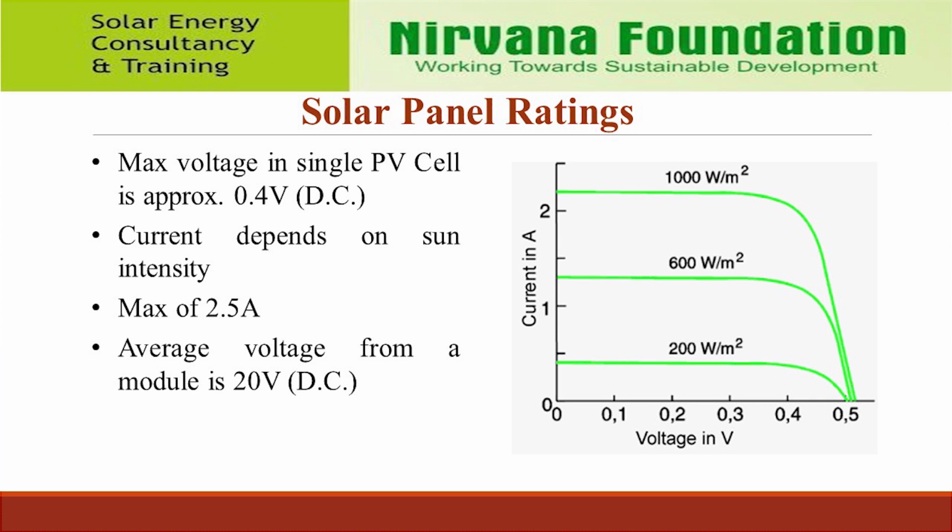The graph shows characteristics of voltage and current of a PV module. It is clear from that as the incident solar radiation level increases, the maximum current for a PV array also increases and has no significant effect on voltage when the temperature remains constant.